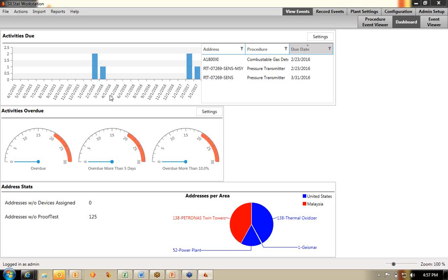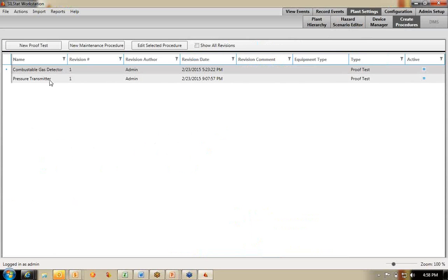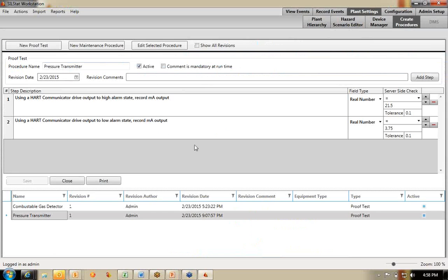Associated with that equipment database are proof test steps for each equipment item, and you can generate a proof test report for each equipment item that is part of your project. You can modify those as you see fit and then use them in SILStat. But that would be part of the import out of Excellencia, not something that you would configure here. Now, having said that, once you get to your procedures here, so once I've created a procedure